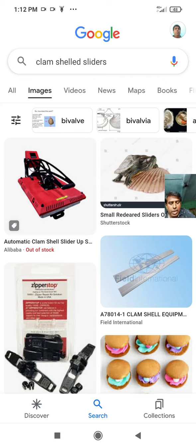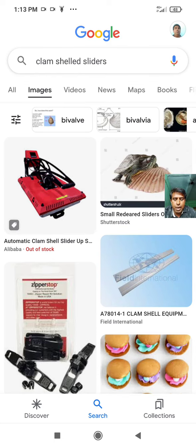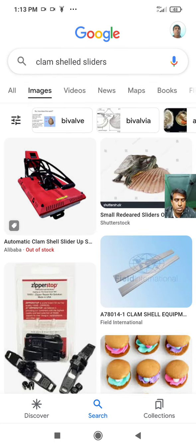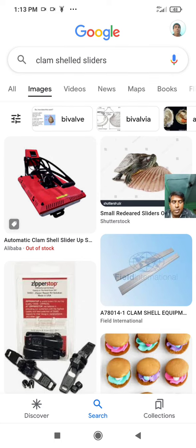Low stitch count can lead to tape sleaziness, and using blunt, large diameter needles will cause heating and melting during sewing because of the high density tight weave inherent in zipper tapes. Improper thread trimming will cause interference with slider action when the loose ends become caught.